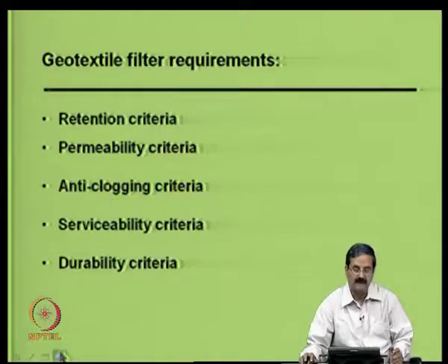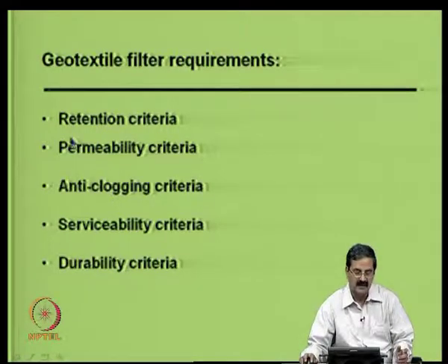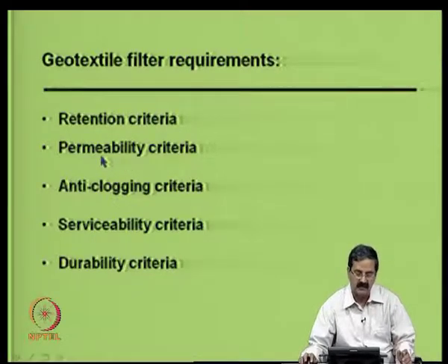In fact, we saw that when you are talking about conventional criteria, which is for soils, you need to consider soil retention criteria as well as permeability criteria, which means that you should not allow the soils to go out of that medium, and also see that permeability is maintained, which is somewhat contradictory. And when you consider geotextile filters, you need to have anti-clogging criteria also, because clogging does occur even in conventional filters.